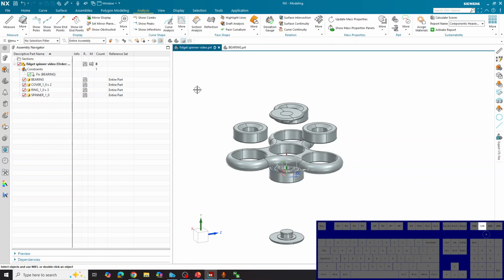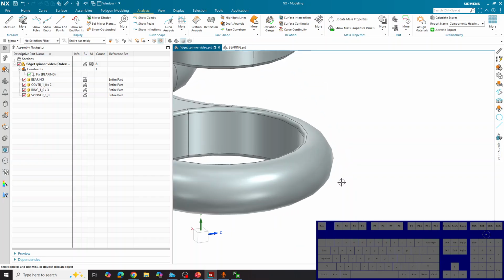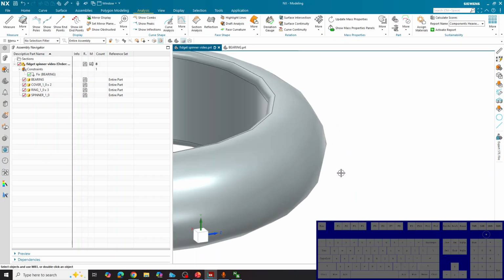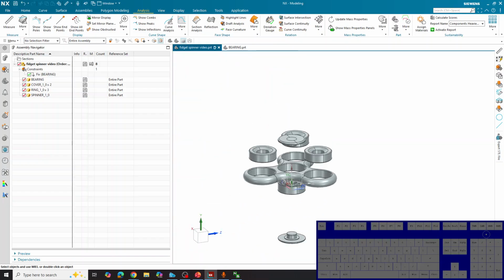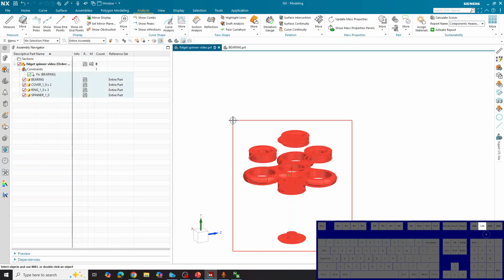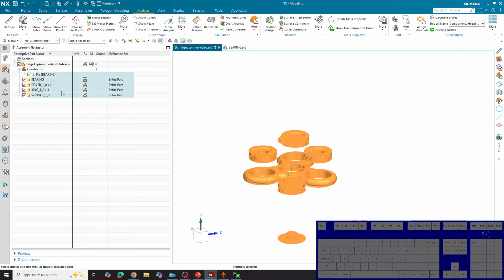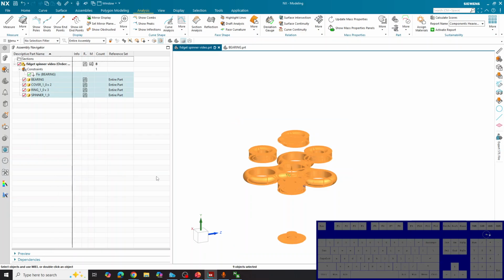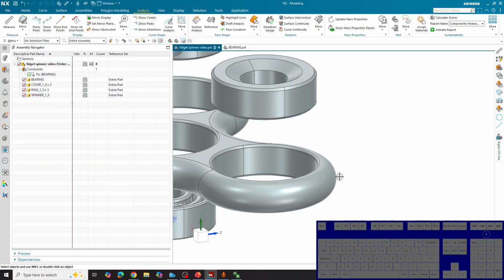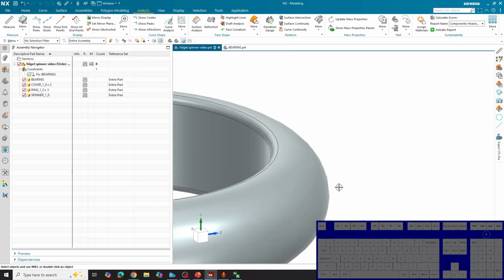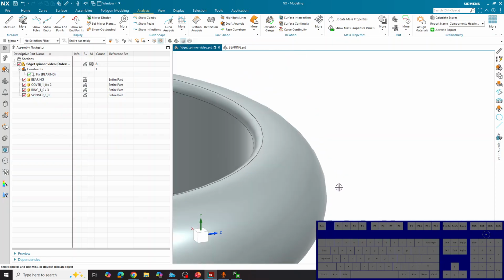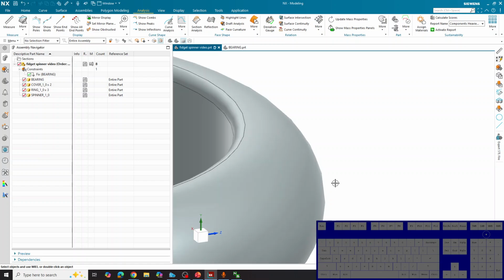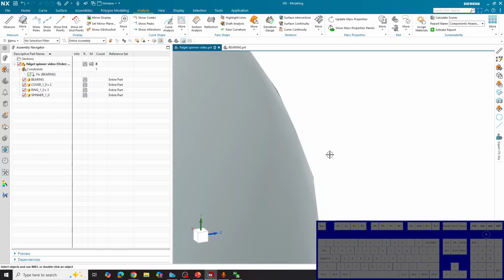And finally, I wanted to show you guys the lightweight and the exact options you have in an assembly. Right now, I don't know if you noticed, but everything looks very polygonal. They don't look perfect. What you can do is highlight everything or just an individual part, and right click over here to show exact, like so. Now your components should show a more precise and refined shape.